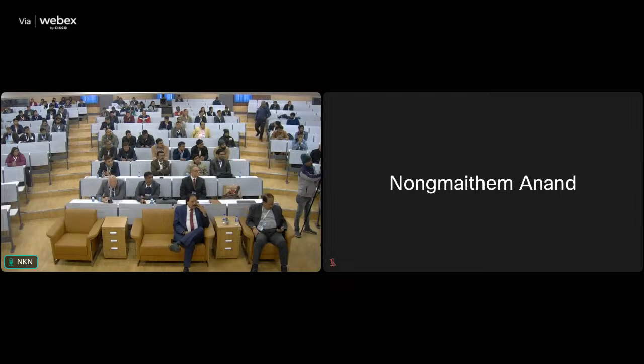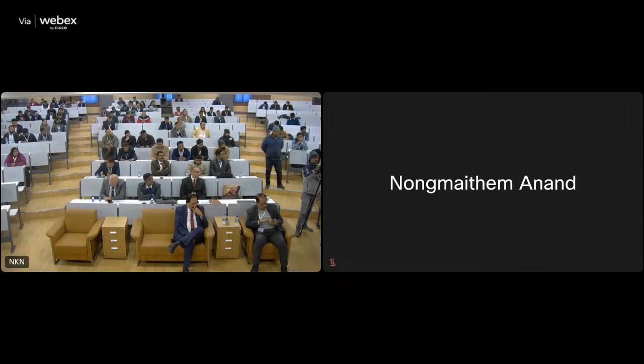Look, you are correct. There will be an effect of this also, and the squeezing condition will reduce. Now, why I am telling you this is that we are expecting squeezing condition in poor rock mass. We say this, okay. What do you mean by poor rock mass? Now, out of our study, we have found that we are expecting a squeezing condition with weaker rock mass having UCS less than 25 MPa, and highly jointed, clay filled joint, weathered joint.